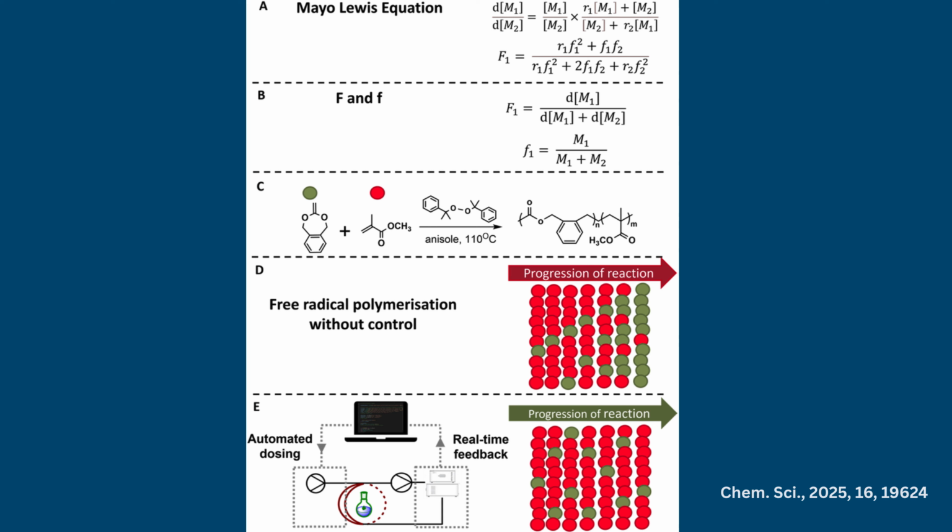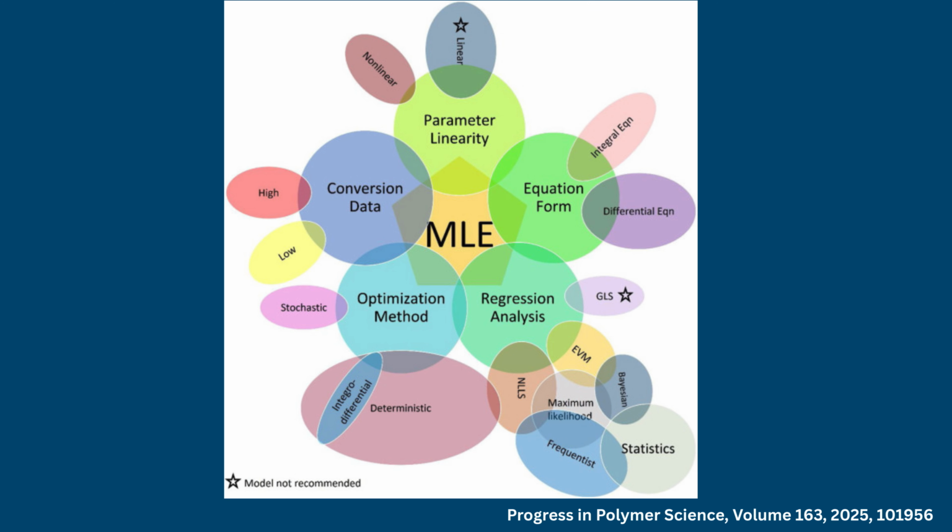In industrial reactors, this challenge is often minimized through continuous monomer feeding or semi-batch operation to maintain a nearly constant feed composition. Under certain combinations of reactivity ratios, an azeotropic composition exists at which the polymer composition exactly matches the feed composition throughout the polymerization. Such conditions are particularly valuable for manufacturing specialty polymers requiring exceptional compositional uniformity, including optical materials, biomedical polymers, and electronic